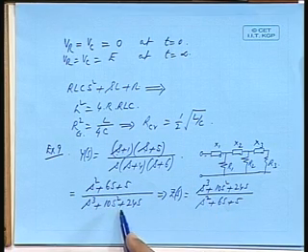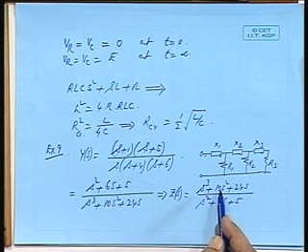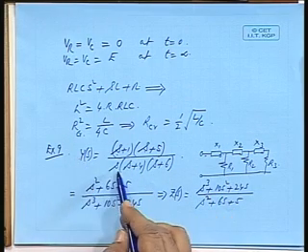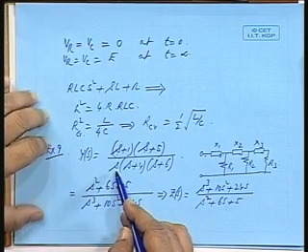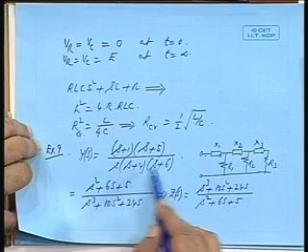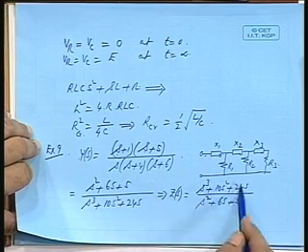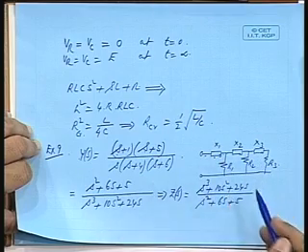Z(s) of this form, is it RL or RC network? Obviously, Y(s) having a pole closest to the origin, closest to the imaginary axis, is giving me RL. It is an RL network. So, this will be an inductance, resistance, inductance, resistance and so on. So, by continued division,